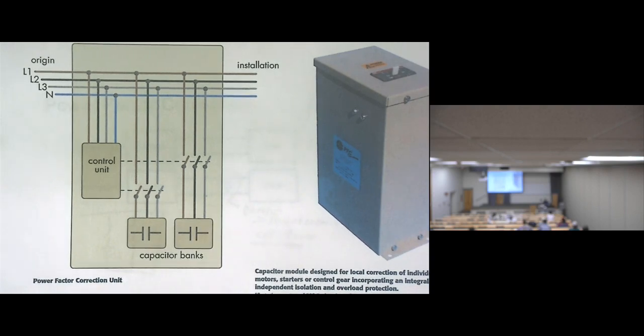Then at night, the factory is off, so we turn off all of these capacitors. I don't need them. They will be switched on if needed. And actually, these capacitors do not only exist in a certain factory or in the industry, they also exist in the utility.